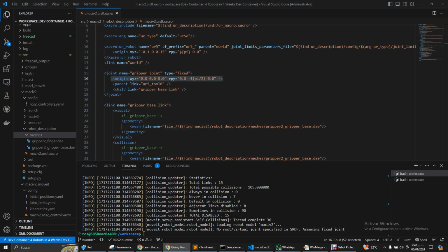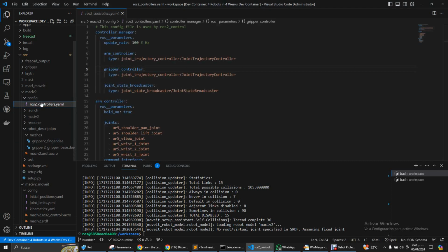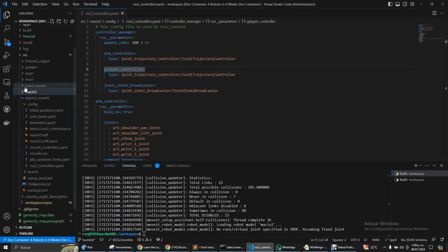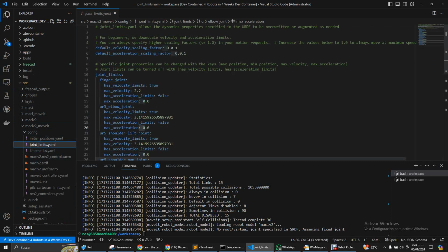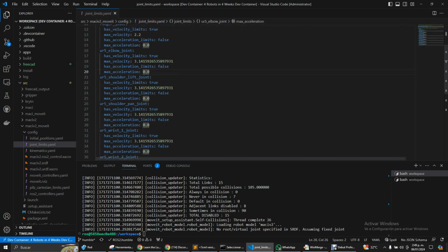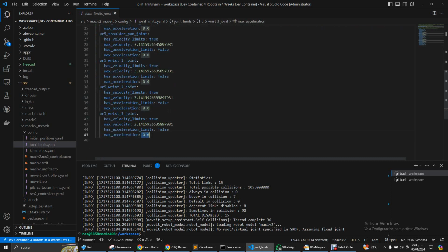Okay, I don't remember where I put it, but for example, another problem that you will have is crashing MoveIt, and that's because on the MoveIt configuration there is a file named joint limits. In this file, everything that is an integer must be a float. I don't know why, because it's looking for a float and is encountering something about the column.